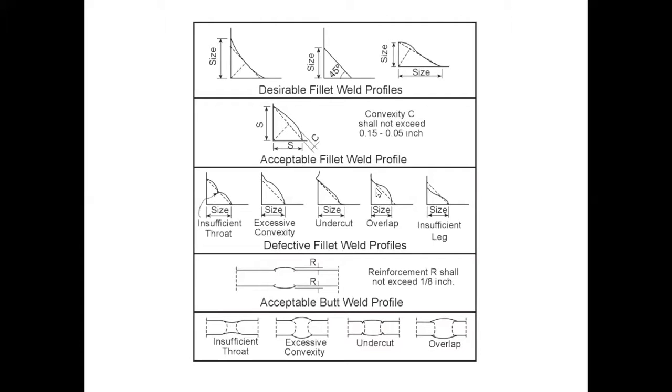Overlap. So, this edge is looking okay, but as we see, the weld is not of equal leg length. So it's a smaller size here than it is here. And that's not what we want, because we want to have an equal leg length if possible, unless we're tapering back welds, then we want a 3:1 taper ratio.